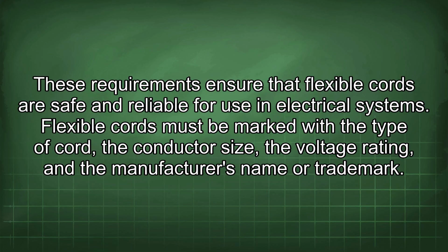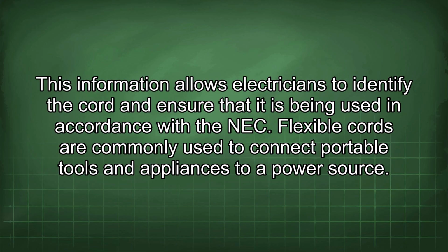Flexible cords must be marked with the type of cord, the conductor size, the voltage rating, and the manufacturer's name or trademark. This information allows electricians to identify the cord and ensure that it is being used in accordance with the NEC.